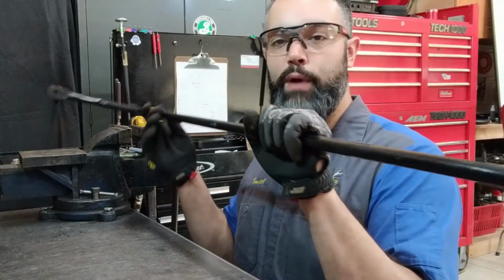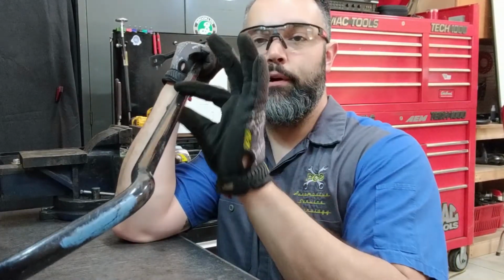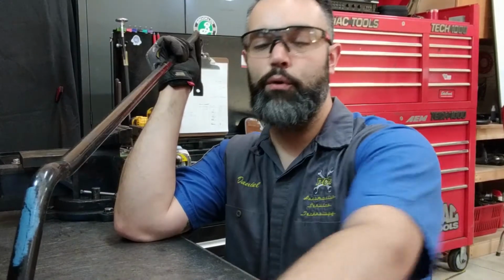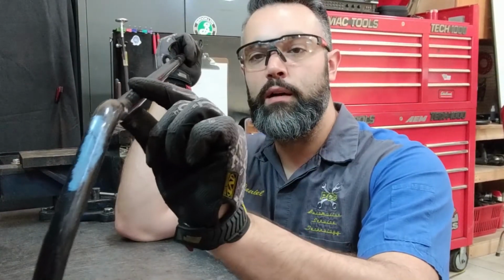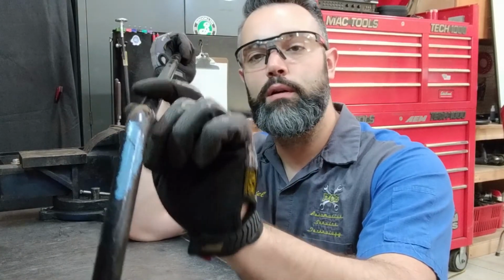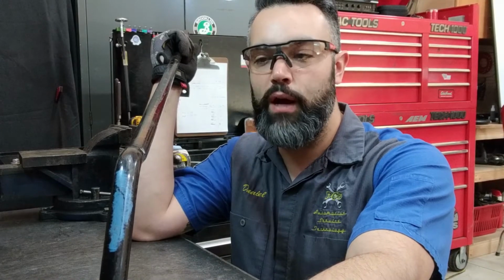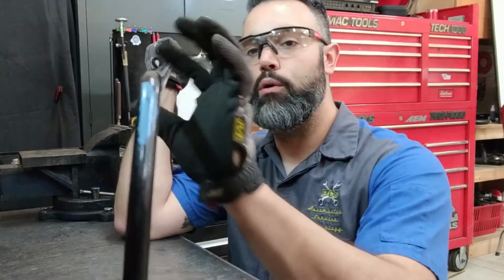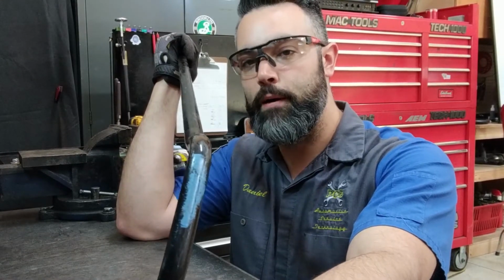And just like on a regular coil spring, the diameter of the bar itself is going to be one method of adjusting stiffness. A skinnier bar is going to have a lot more deflection in it, so it's not going to be as stiff. So a bar that is thicker or wider in diameter is going to be a stiffer sway bar.